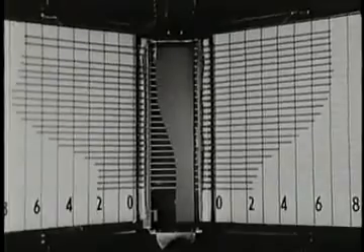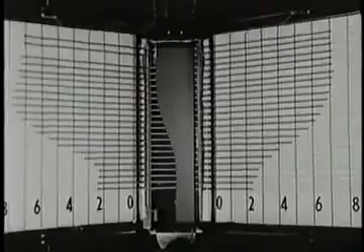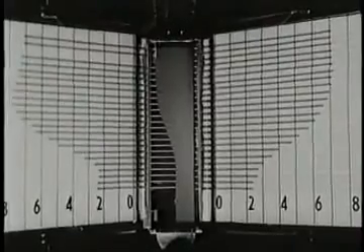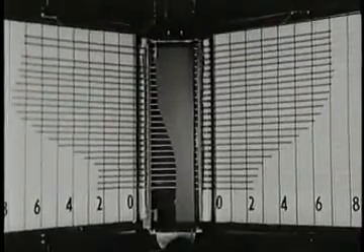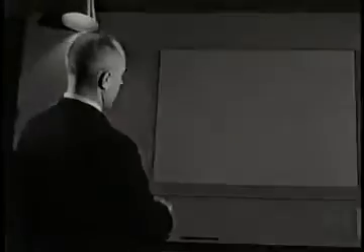Bernoulli's integral is based on many restrictive assumptions. The statement that high velocity means low pressure is only sometimes true. Let's see how one could go astray. This straight duct has a partition. One side is free and clear. The other side has a flow resistance. Downstream of the partition, the two streams rejoin.